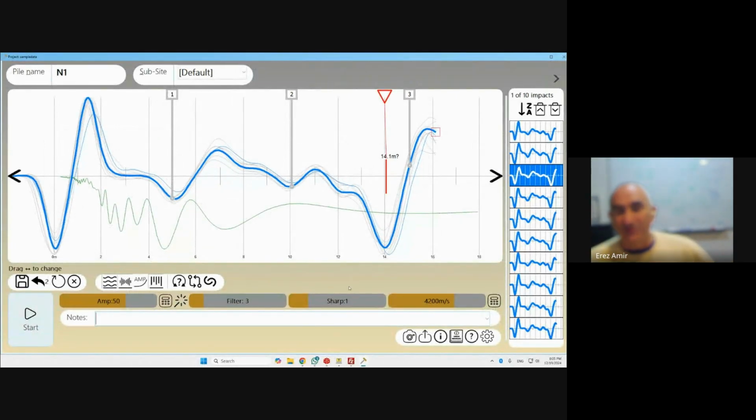When you have a top defect in the pile, or one defect, it's very hard to see anything below that. I showed you that in PileWave, and you can see that in many examples. Usually, if you have one defect, you're lucky to see anything below that because the repeating waves are just mixed, and the best that you can do is sometimes see the end of the pile, sometimes you don't see anything at all.